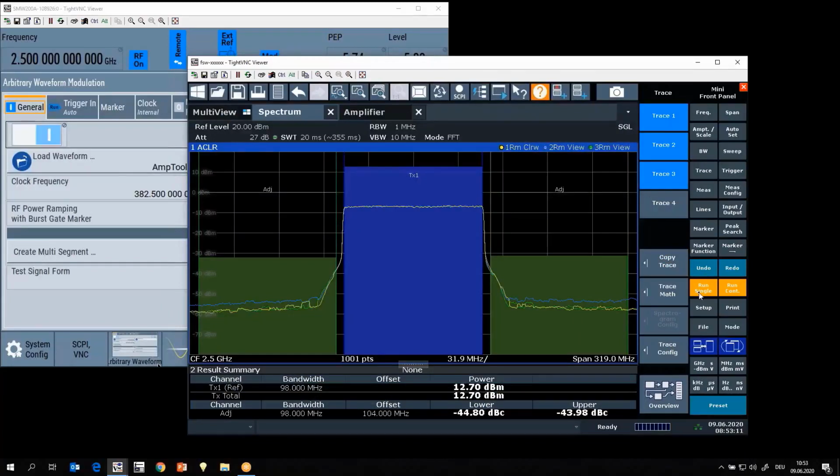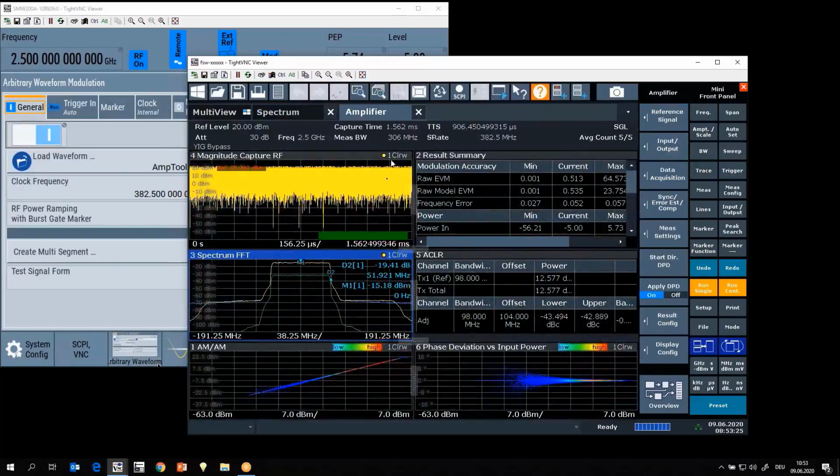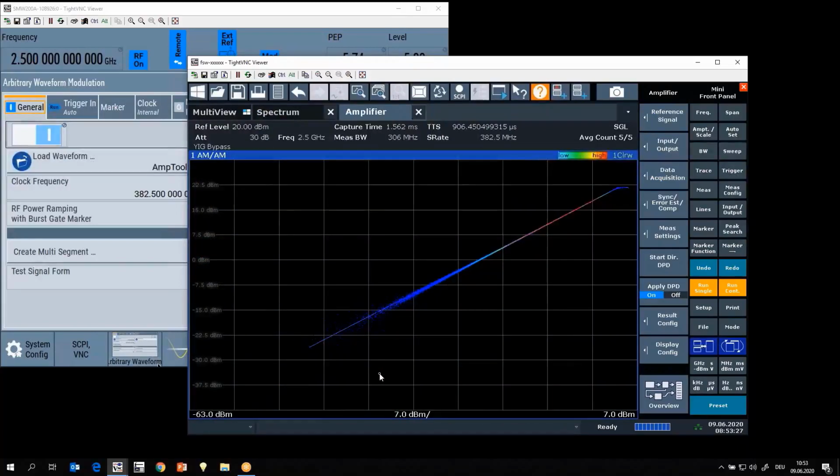So there is now, the blue one was direct DPD without anything. The green one now is direct DPD with IQ averaging. And as I said, it's not only the signal shape itself, basically the original filter, that causes the ACLR to not further drop, but it's also the artifact that you can see up here, the hard clipping, which is a key characteristic of the DPD as we're doing it in K18.